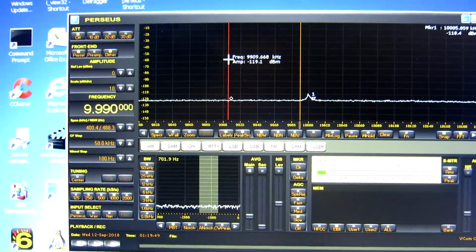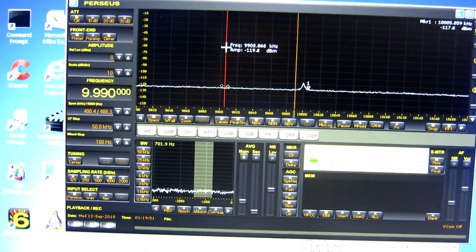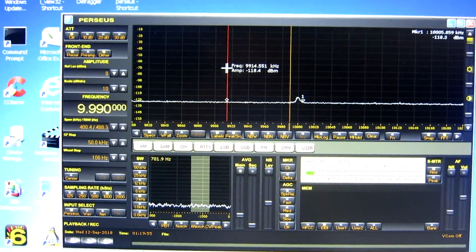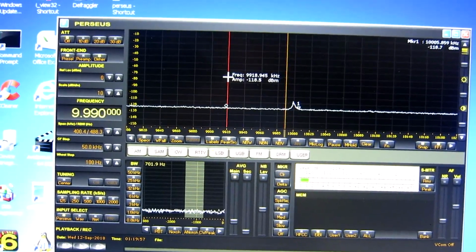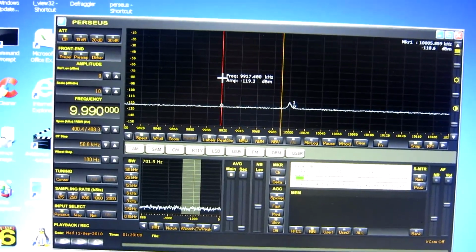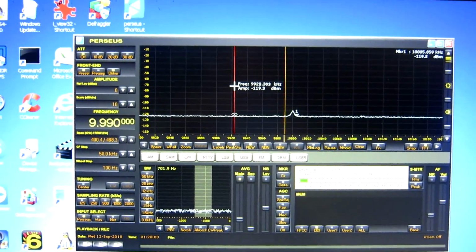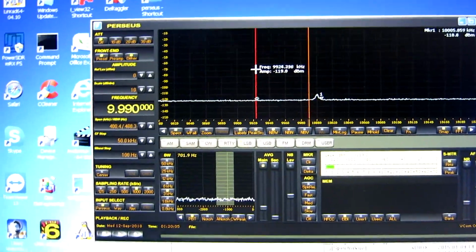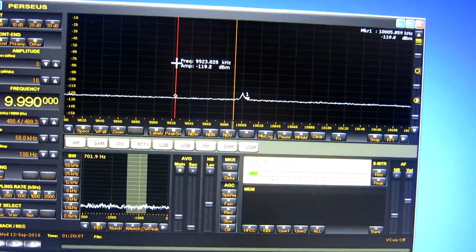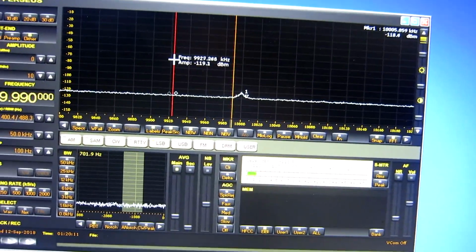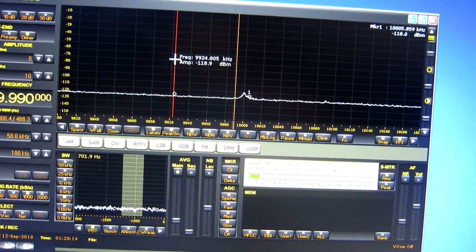I mean, it's a grounded grid amplifier and it doesn't produce any noise on the output side when the impedance on the cathode is high, which it is outside the resonance of the crystal filter. This is with the 2-section filter, and I can connect the 1-section filter, and the difference is small.